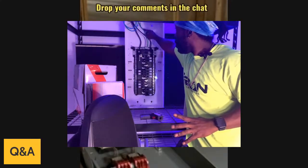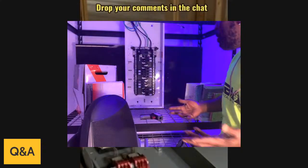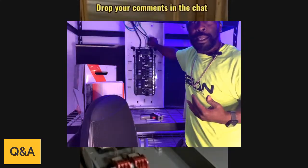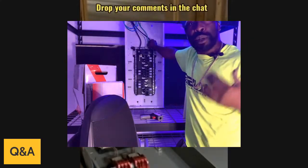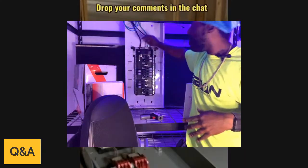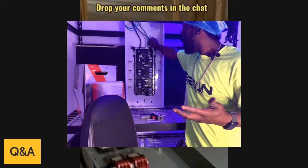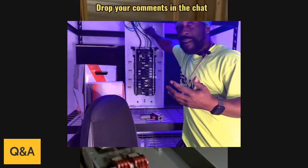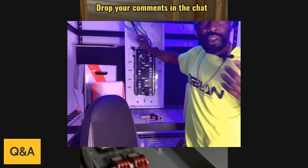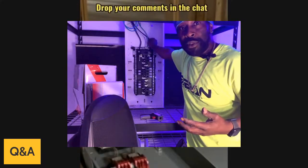And also, as you can see, why I use the green wire instead of a regular copper cable. If it was a regular copper cable, you're forced to insulate this cable here. So always remember, if you are going to be dropping your cable in as a ground wire, bonded in, you have to have it insulated. It's a requirement. You cannot just drop a bare copper down this sleeve right here.